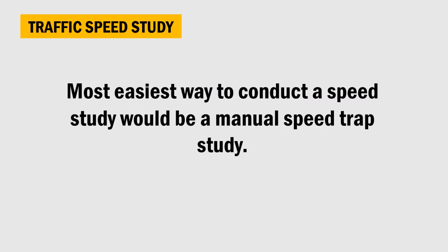Let's talk about traffic speed study. One of the easiest methods to conduct a speed study is manually. In this method, we set a test length in a stretch of road and record the time for each vehicle to go from end to end of that test section. Using the time data and the length of the test section, we can determine the speed.